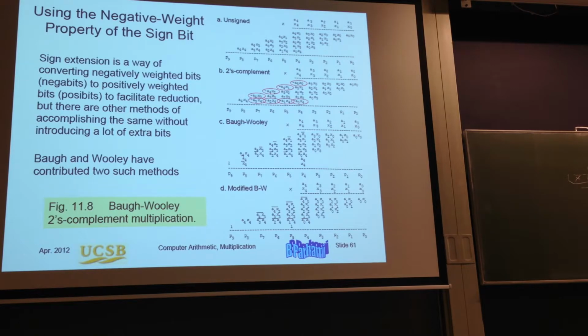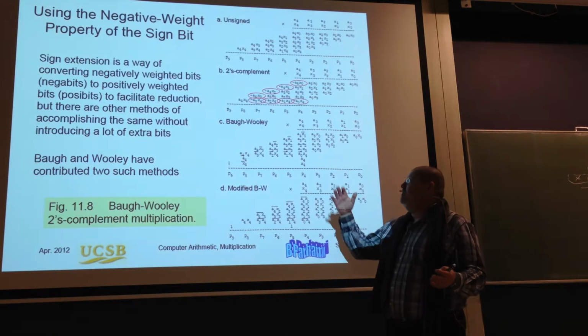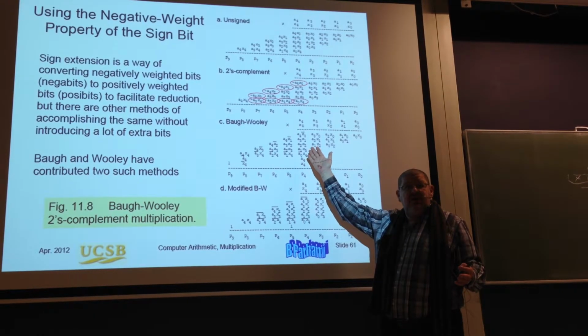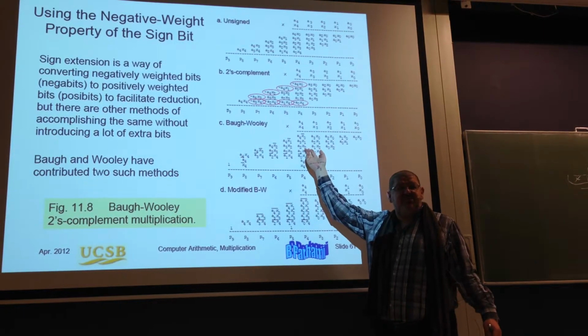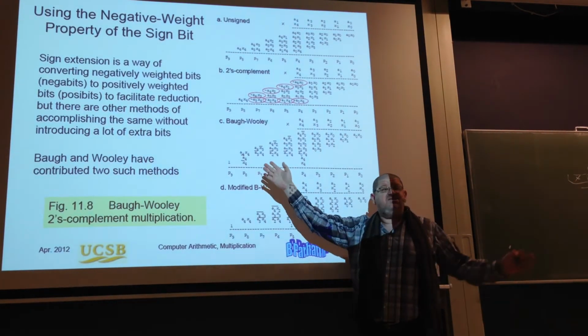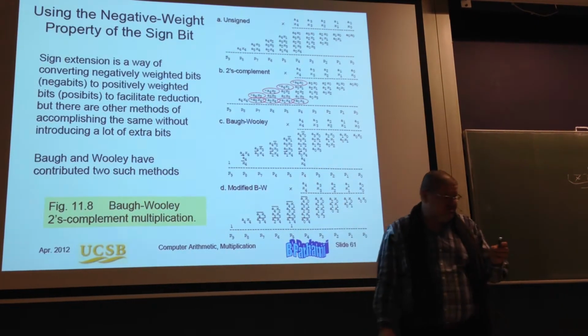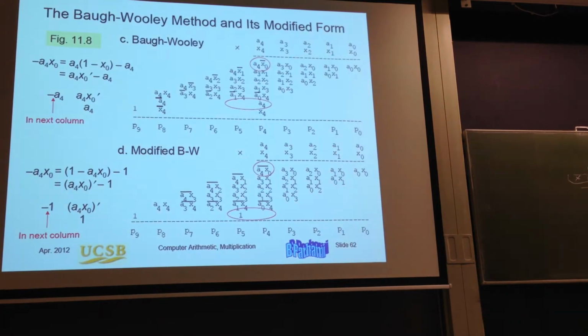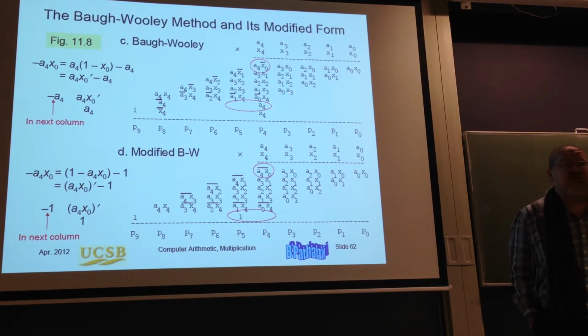And now, those guys came with approaches which they said, okay, what I'm doing is I'm replacing those with a bit of extra calculation in the generation of the partial product, and some kind of extra signals which are compensating for that. And this is one approach, this is the other approach. And each of the approaches is based on some kind of simple manipulation which we are familiar with from 2's complement.